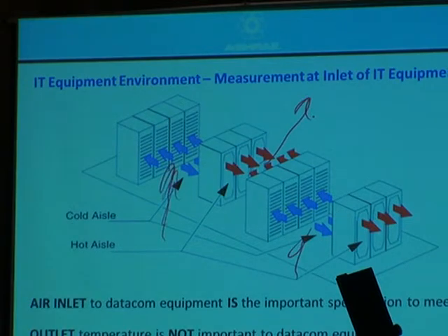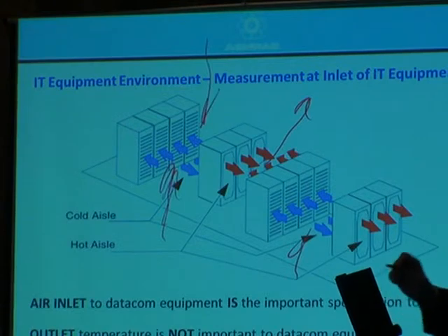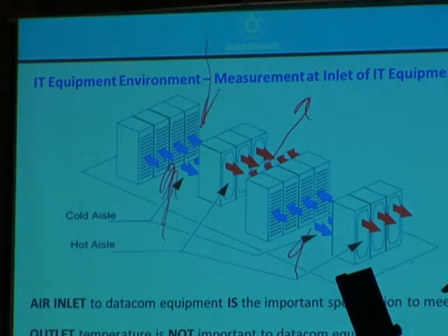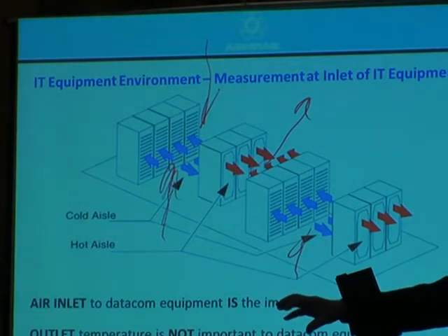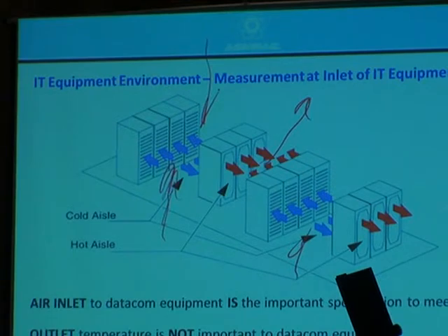Okay? So you get the setup, cold aisle, hot aisle, best practice, and then cold air could be distributed from overhead. Rather than a raised floor, you could have just this floor, and these chairs or the racks, and the air would come from ducts from the ceiling. Okay? Still cold aisle, hot aisle. So what are the requirements again? The requirements are recommended 18 to 27, 27 max. And I'll talk more.